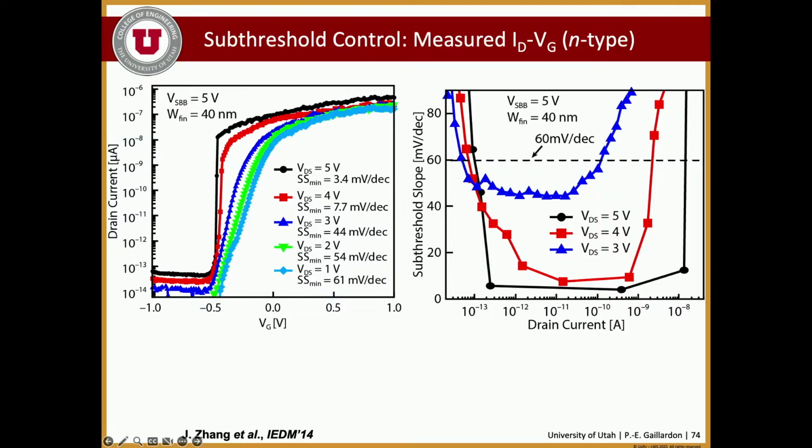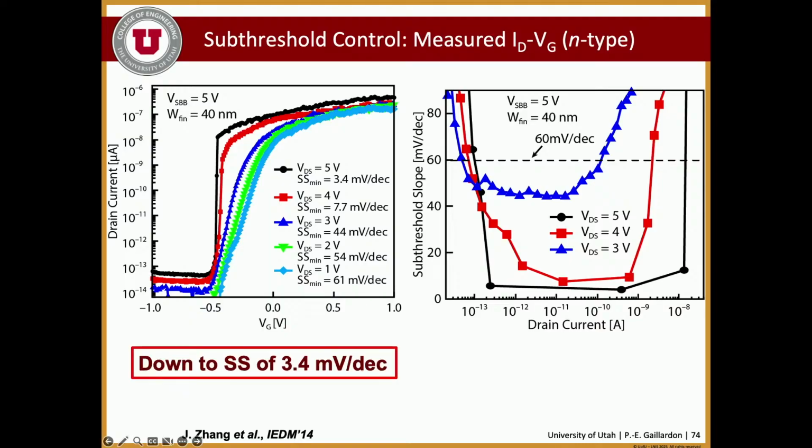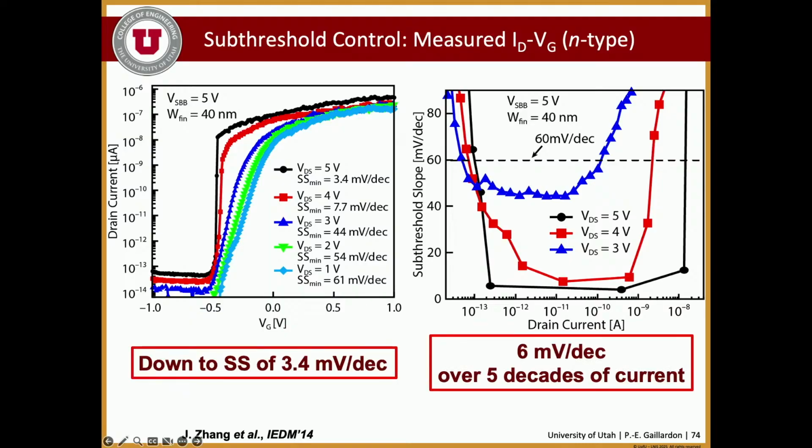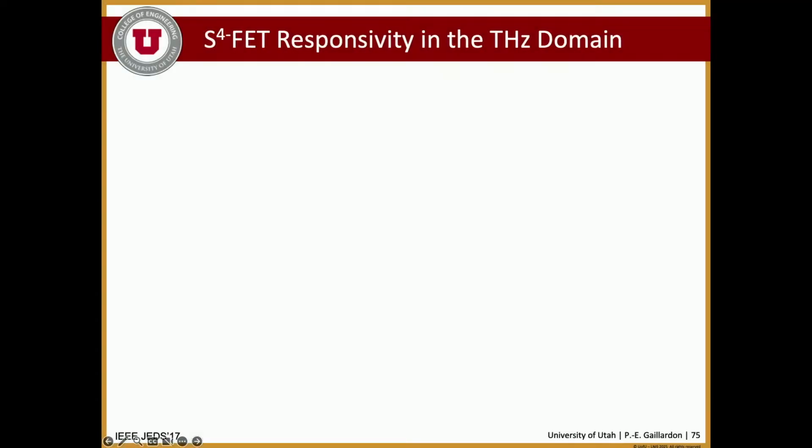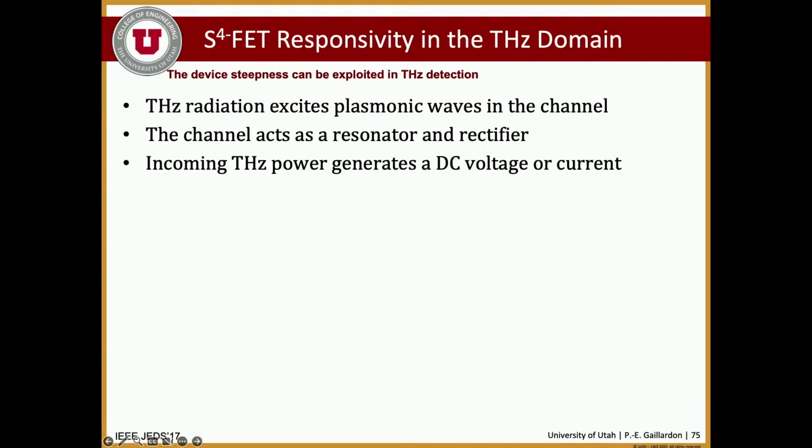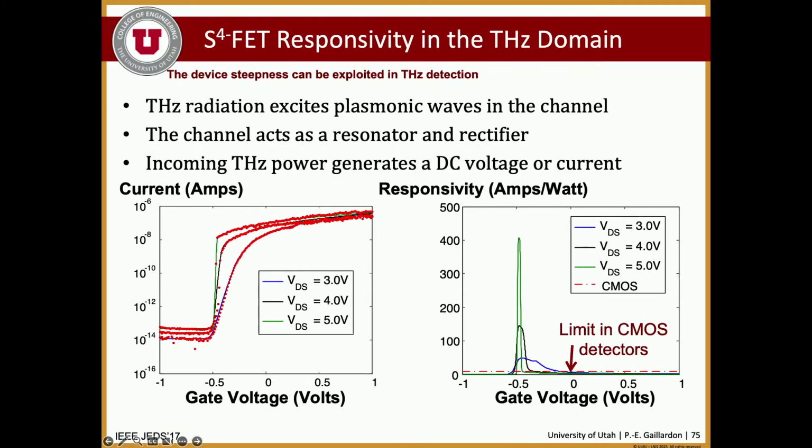So dynamic power consumption has a quadratic relationship with voltage, so you win there. It's not expected to be the case very much with these devices because you still need fairly large voltages to bias your gates, but nonetheless, you get very, very steep behavior. And that steep behavior, even if you cannot directly rely on it to reduce VDD, has very interesting applications for RF or for analog devices, right? Because your transistor will have a very steep gain right there.